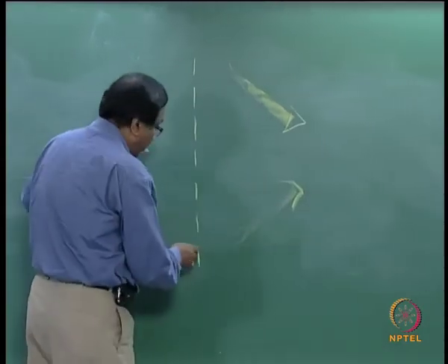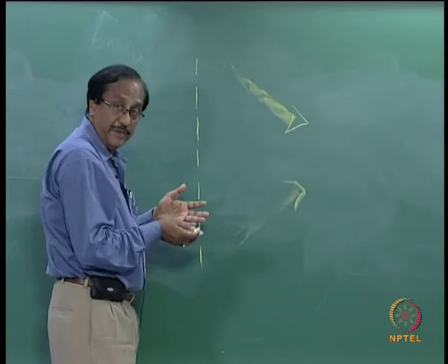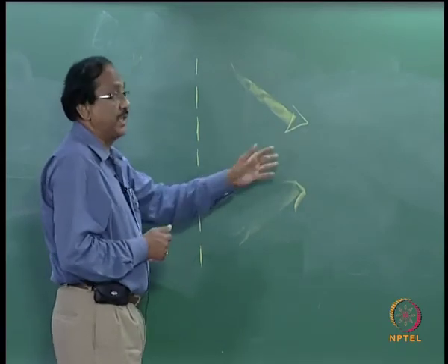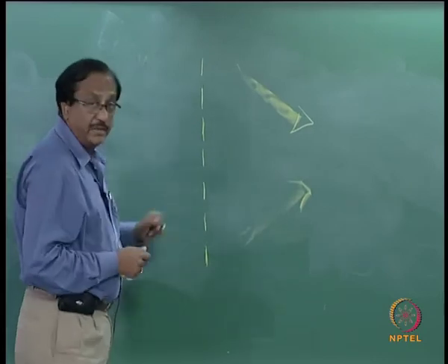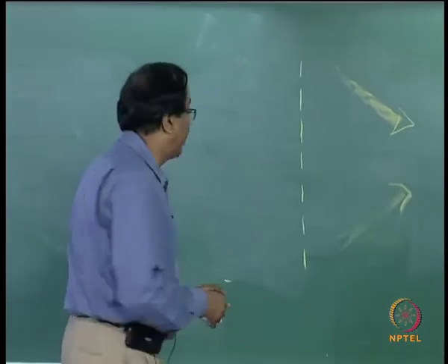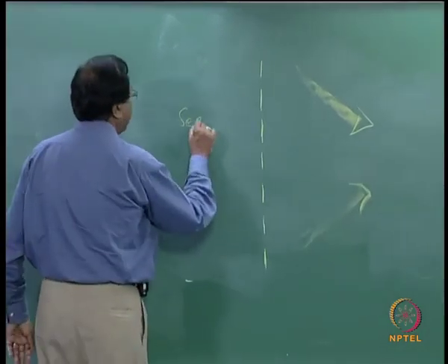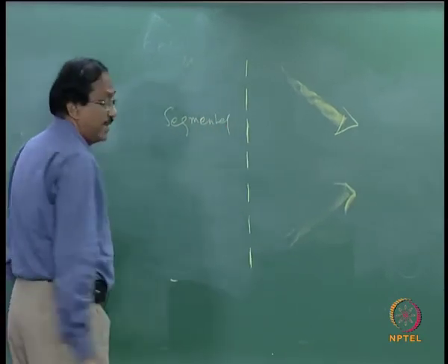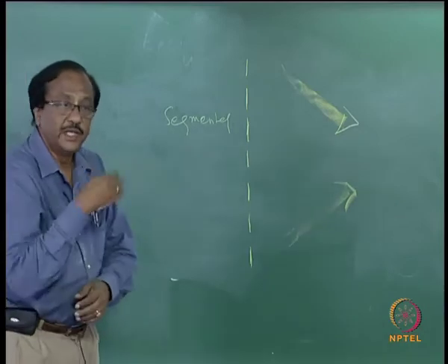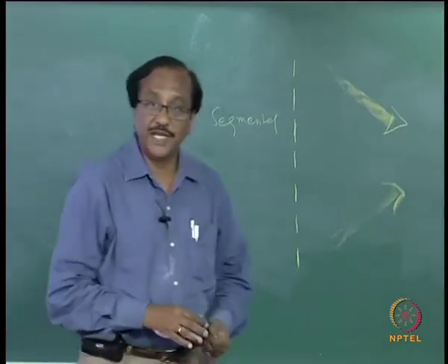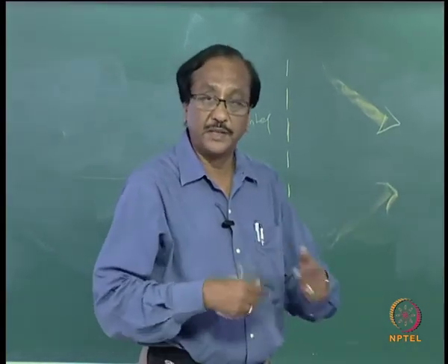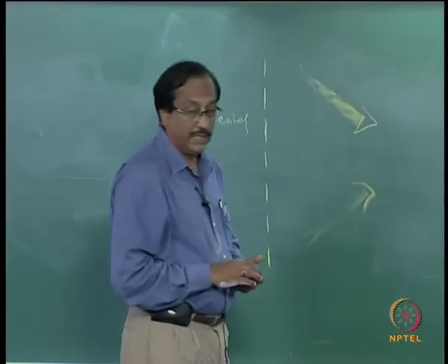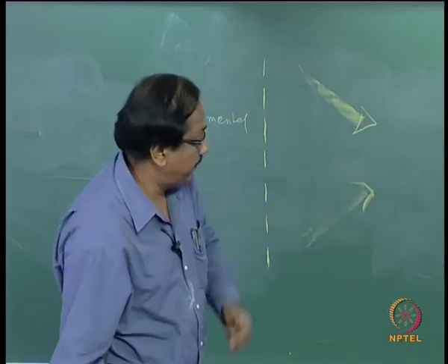When you want to do that, waves with different amplitudes and frequencies are approaching from different directions at a particular location, and you need a multi-element wave maker. It is also called a segmented wave maker or snake type wave maker, because it moves like a snake when you set it in motion for generating directional waves.